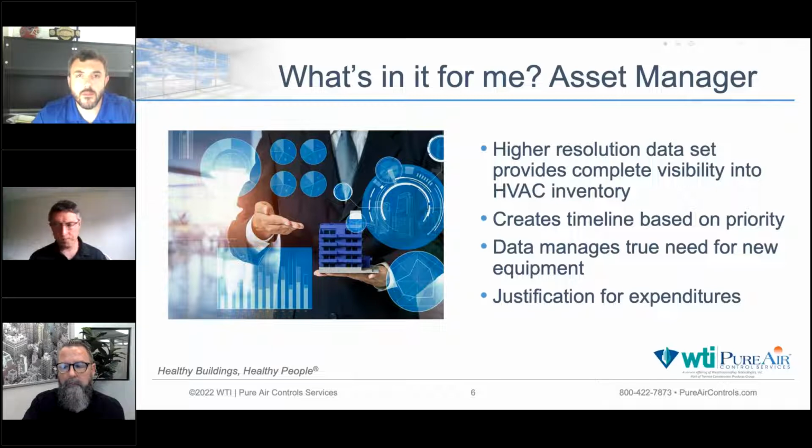I said to him, well, wait a minute. You have multiple air handlers all feeding this area. You have a significant amount of ductwork in the end. Rather than rush in and do all this cleaning, let's go through the system real quick and take a look and identify where our source is. Let's get that source and then come up with a plan to clean or remediate.